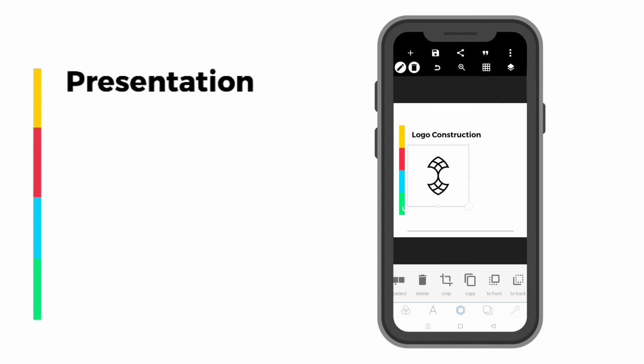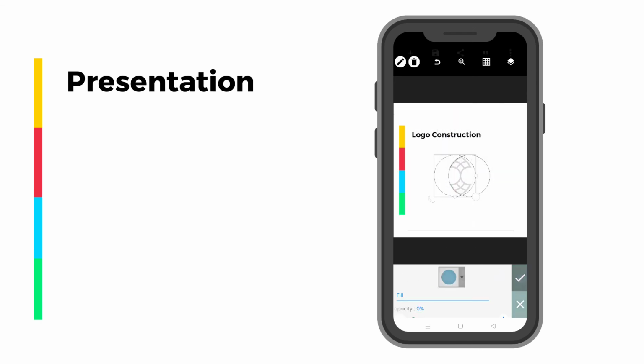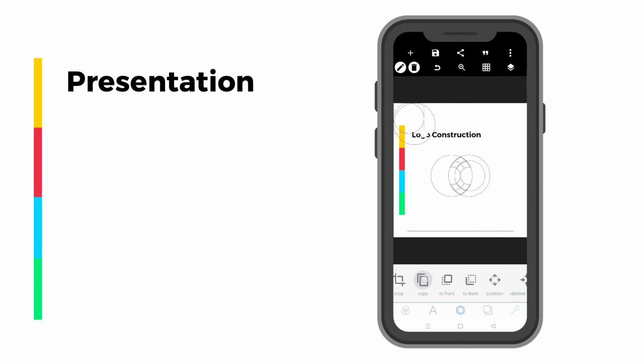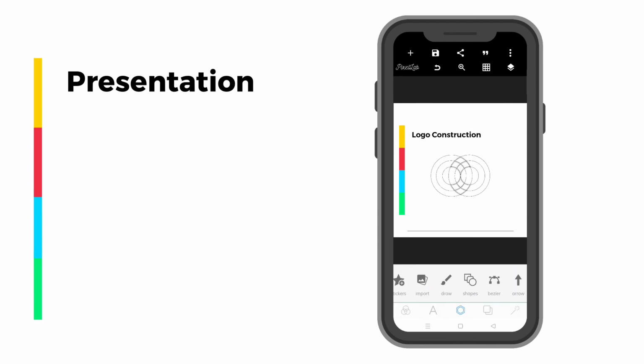The first thing I wanted to present is how I constructed it. I had to pull out a circle, because this was created with circles. Then reduce the opacity of the circle down to 0. Then go to the stroke section, increase the stroke to just 1 and make the stroke black. Then I start matching everything until I have everything complete. And also don't forget to rotate it counterclockwise by 90 degrees.